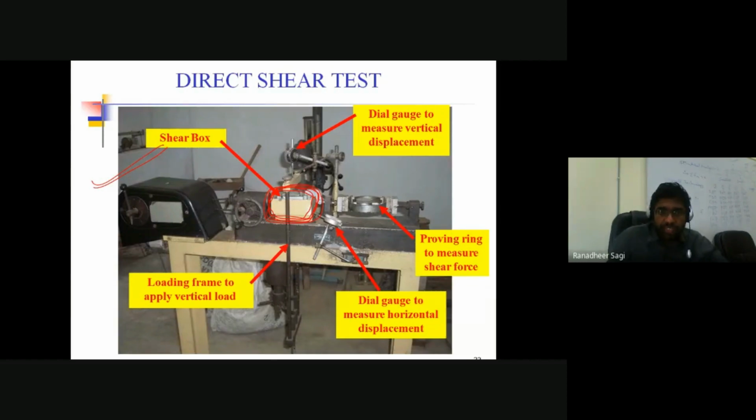On top of the direct shear box, as I said, through a loading frame, you could see this is my loading frame. Through the loading frame, we are going to apply vertical loads onto the soil sample. You will have some circular loading discs hung to the loading frame at the bottom. From that circular loading disc, whatever load you have applied gets transferred through this vertical member and ultimately gets applied onto your direct shear box through the contact of the loading frame with your steel ball, which is immediately on top of your pressure plate. From the loading frame, load gets transferred onto that steel ball, and from that steel ball onto the next. Ultimately, a uniform pressure distribution is assumed to be applied in the vertical direction on the soil sample.